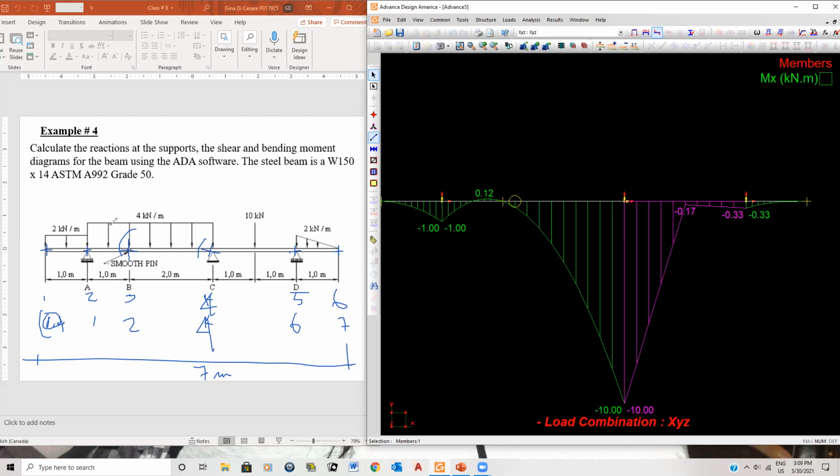here is the distributed load, therefore it's parabolic. That's what it is. Here's the distributed load, therefore it's parabolic. Here it's a concentrated load, therefore it's linear. And of course, here what's happening. Okay. So then, well, here it's somewhat linear, you understand? Unfortunately. And then after that, here it becomes, believe it or not, cubic in here, okay? So there's my moment diagram.